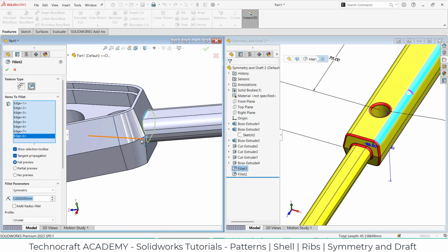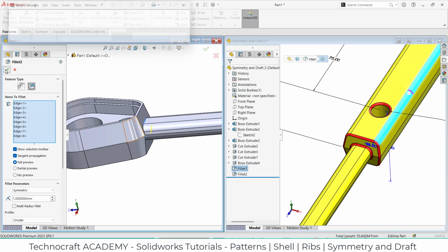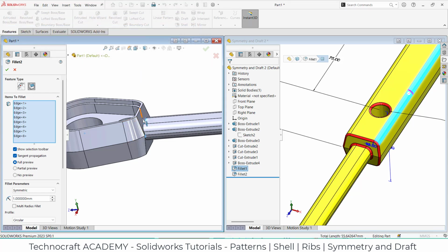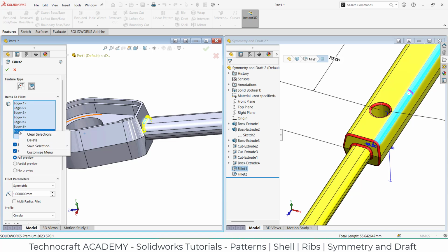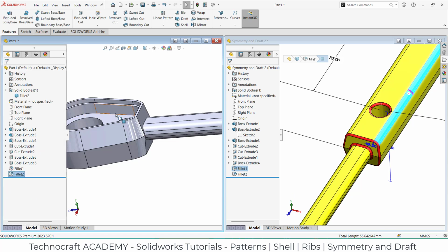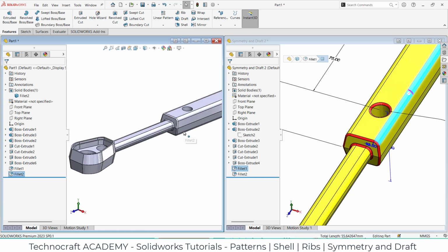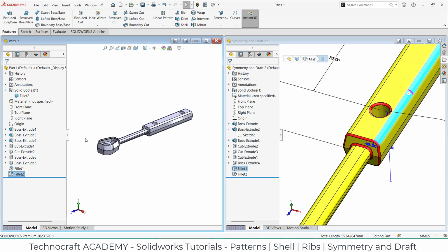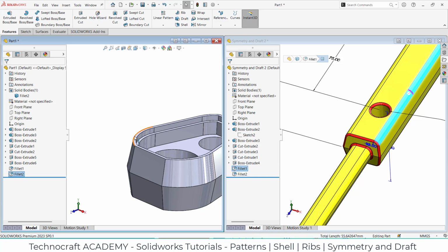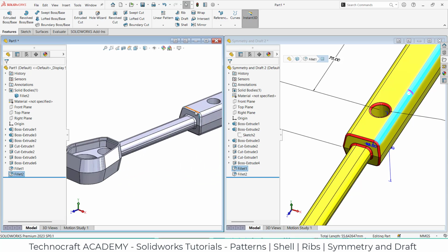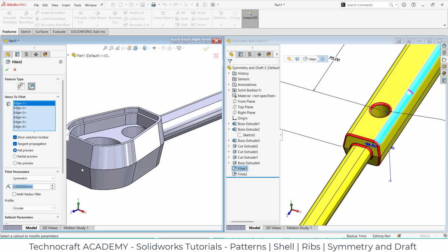And sometimes due to some issues it might not extend. Let us see. Don't think it will create. Yeah, right. I need to delete this and this will create that later. This side it is done. And finally here I would like to have the same fillet radius. I can again select this one and edit.